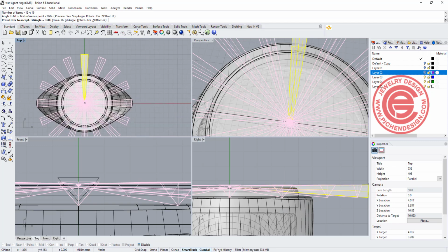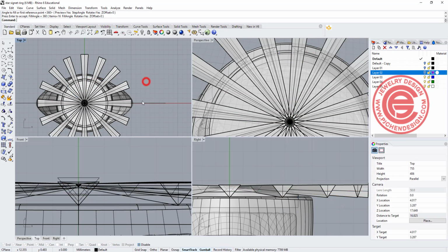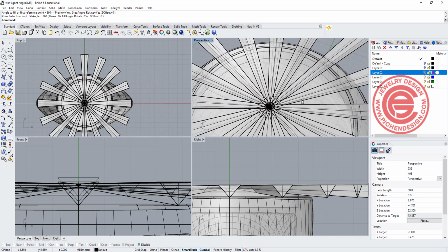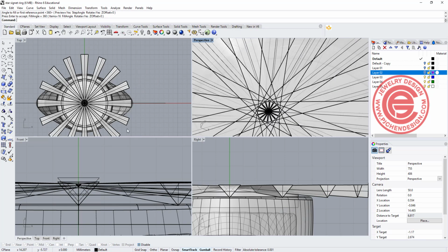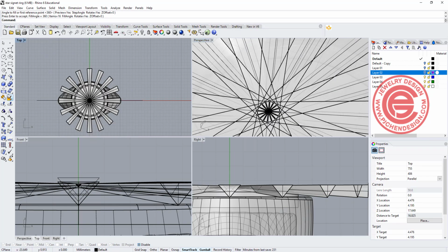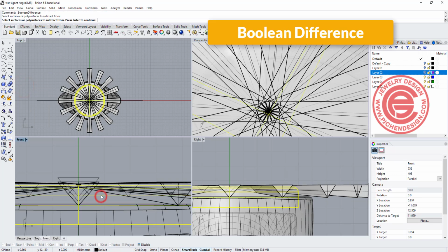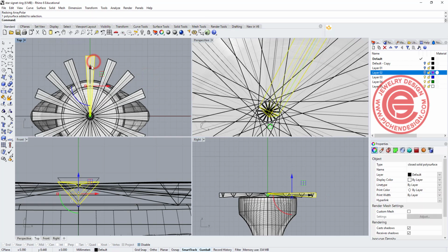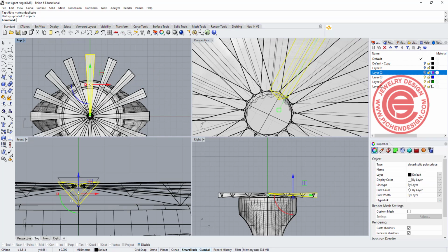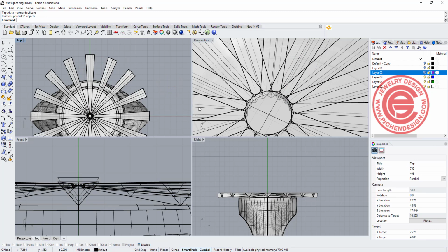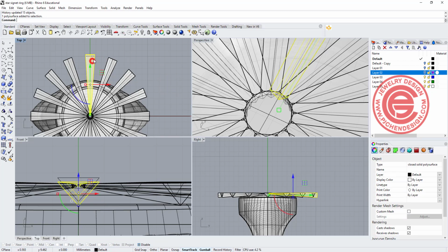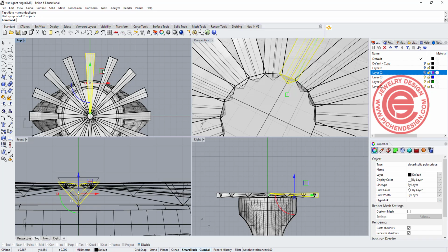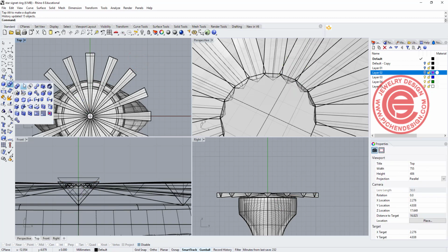So I also want to record a history, and let's click OK there. I may have a problem because all the seams are connected there, but we can give it a try and see how that works. So let's go ahead and do the Boolean Difference, this one, out of all the patterns that we have here. Okay, so we do have a Boolean issue. I will suggest moving this one up just a little bit, so it's not completely lined up over there. Maybe up even a little bit more there.